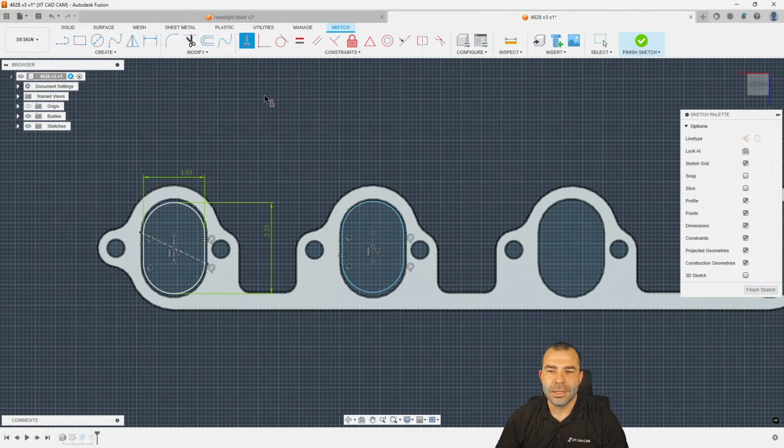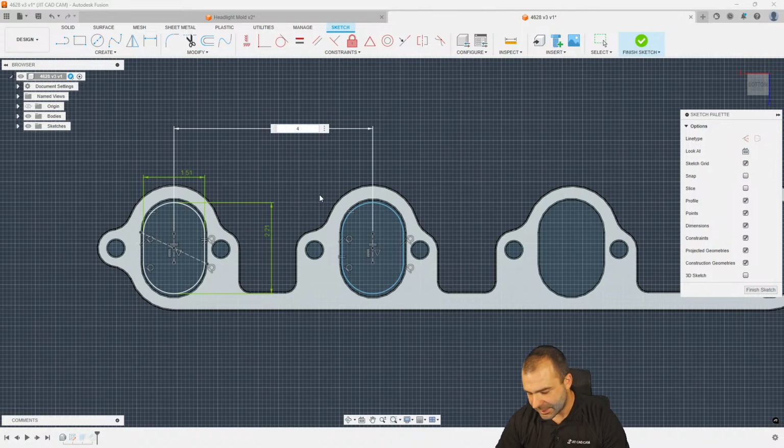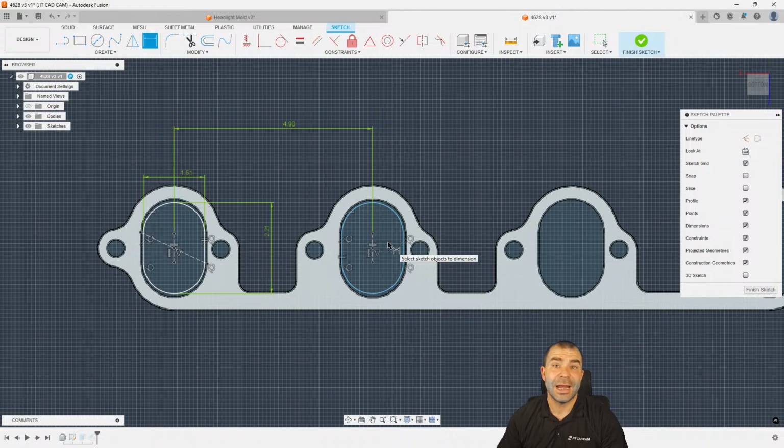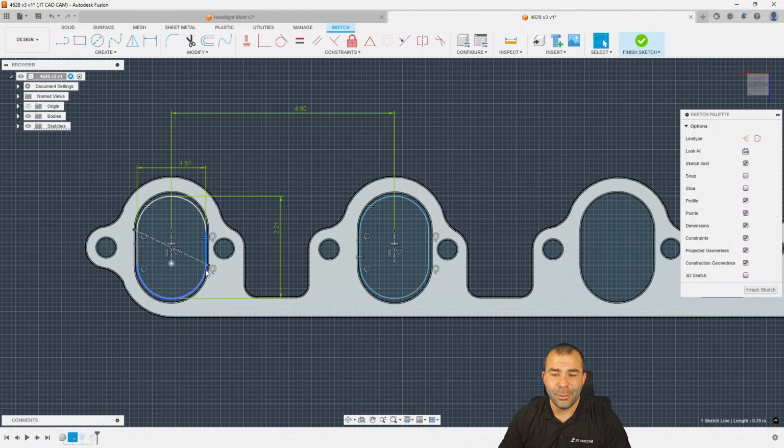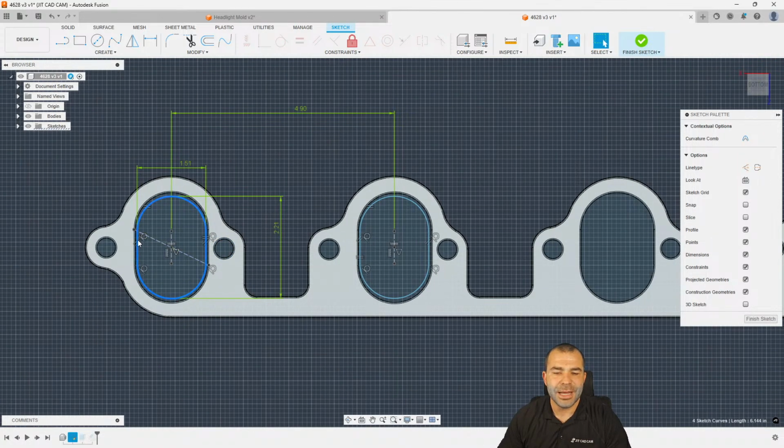Now, with a horizontal vertical, we can align this horizontally to one another. And then the last thing I would do, if I knew the spacing based on this part, I could go through and do my port spacing, which in this case is 4.9. Again, placing that next slot. I say slot in this scenario because that is the tool being used in the sketch environment, but what that tool is allowing me to do is to recreate the second one based off that actual first one.